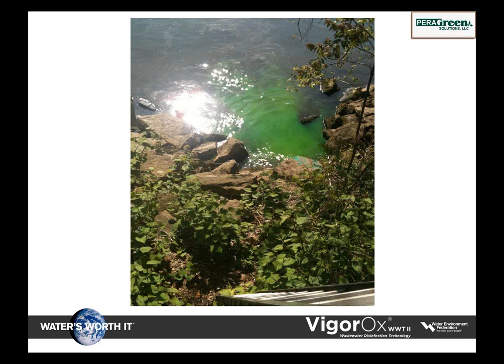So that's important here, because what it shows is now we're dealing with a background in the receiving stream. Is it interference? Is it actual halogens that we're testing? There's a power plant upstream. There could be brominated products that are part of that. We didn't have enough information to test it, but we did see the receiving stream had a background TRC level that we had to take into consideration.